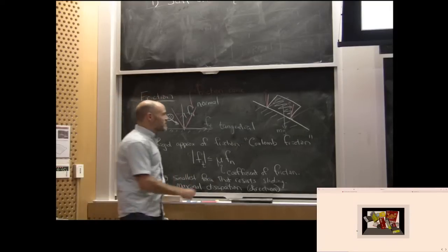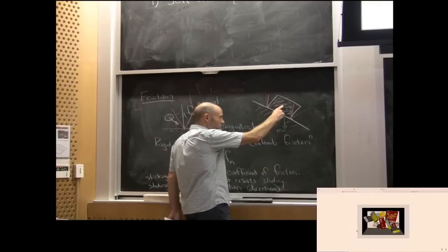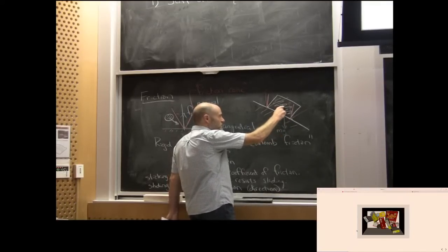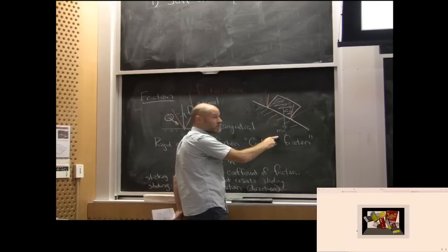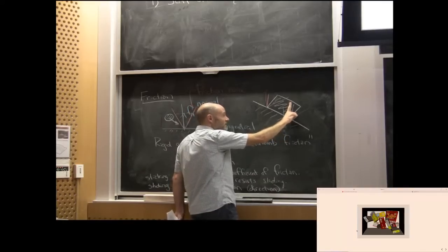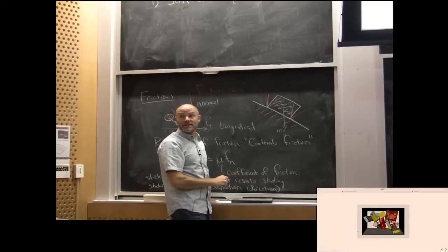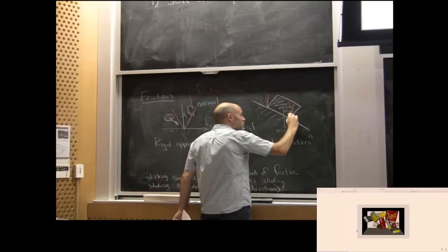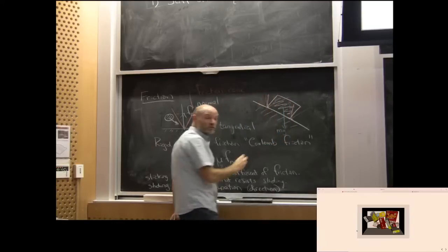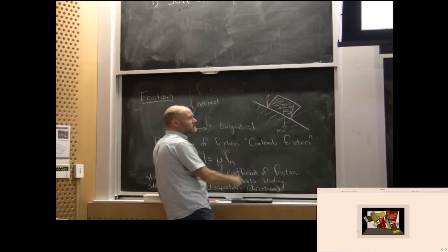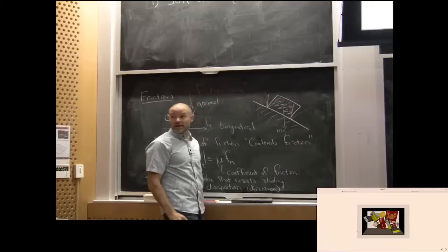Exactly. So if I were to make a free body diagram, which I'm doing here, and I said I wanted the forces to balance, then in order for the forces to balance, the forces of contact would have to be able to be equal and opposite to the force of gravity. And because that is not an acceptable friction force, that means that it would slide. In fact, the friction force you would get would be on this line, resisting as much as possible. That's the maximal dissipation idea. Resisting as much as possible, but ultimately still not stopping it from sliding.